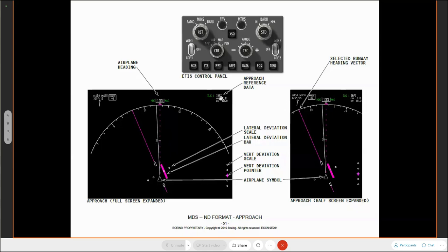Again, we've got ILS selected, so we've got the ident for the ILS, we've got the DME, and we've got the course that we've got selected on here, 111 degrees. Okay. So again, ILS don't always have distance measuring equipment. If they do, it's automatically tuned when you tune the ILS. All this here is to do with ground speed, indicated airspeed, and also wind direction and wind strength. Okay. Again, pretty much standard on most modern aircraft these days.